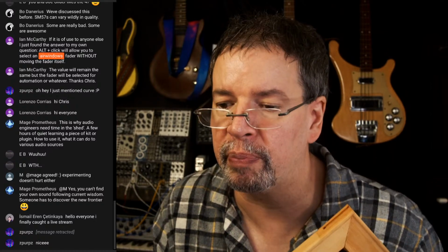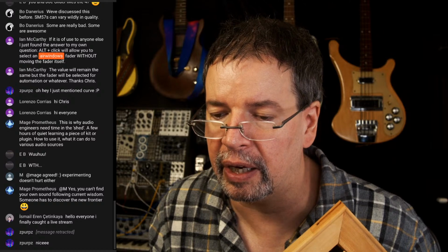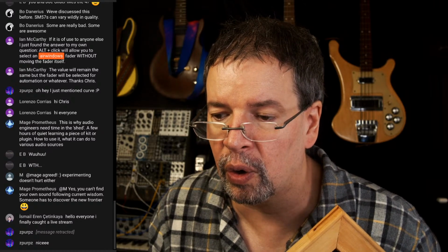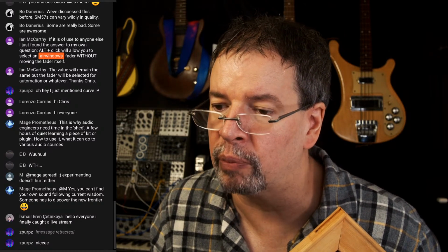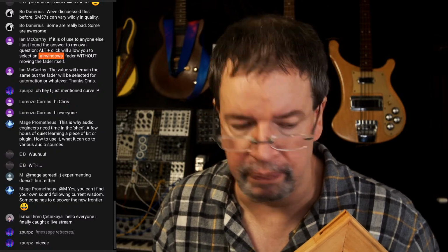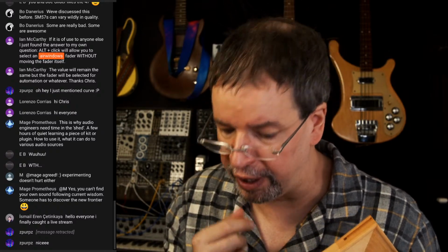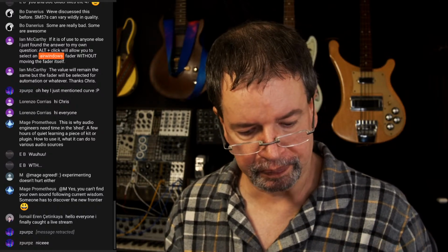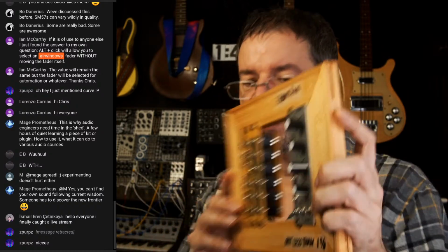You should probably also build in either a fuse or some 0.1 ohm resistors that will blow up if you wire stuff wrong, because that way you don't kill the actual power supply when you short stuff together by mistake. So here's the thing.